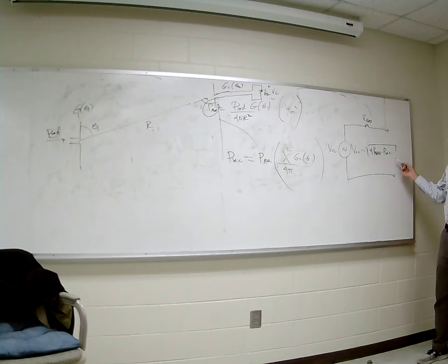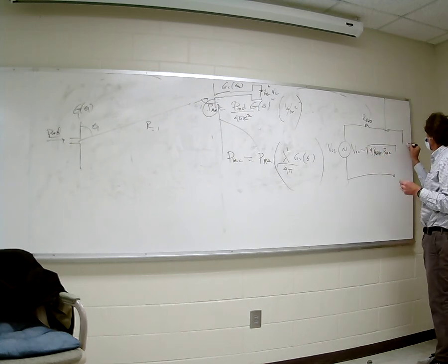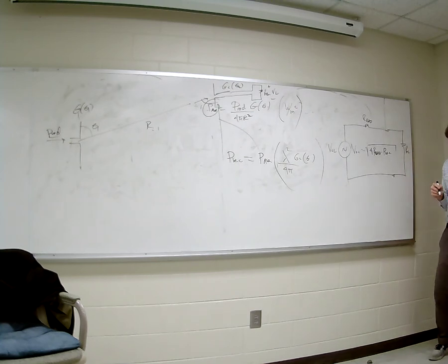Now once we have the open circuit voltage here, then for any load, for any given RL, you could figure out the current by taking VOC divided by the series resistance. It would be a peak current. Do you agree, class? Or you could figure out the power. You could take the current squared times R and divide by 2, correct? You could take V squared over R times 1/2, but that's how you would get it. You with me, class? How many see this? That's it in a nutshell.